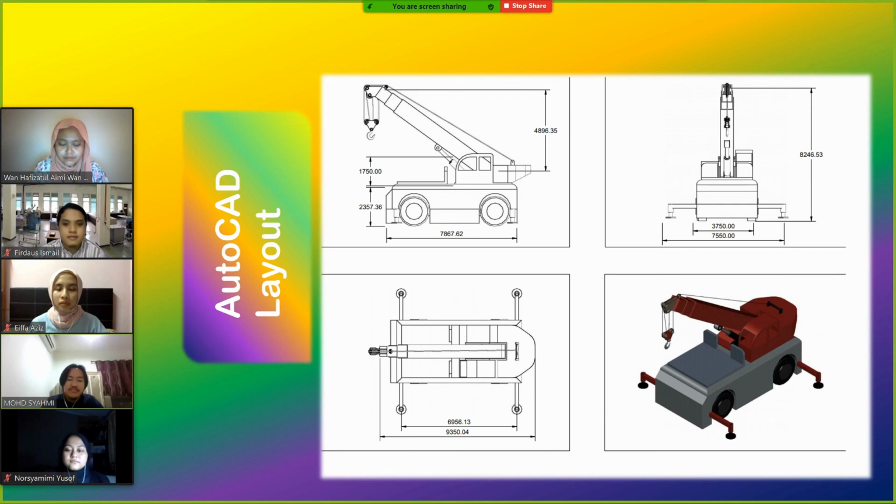We innovate a little bit in our design by inserting a platform with brick clamps to hold a pallet of bricks. We inject this mechanism in our design to place the bricks on it before the load is uplifted. The function of brick clamps is to prevent the pallet of bricks from moving when it is on the platform, and also for the safety at the construction site.